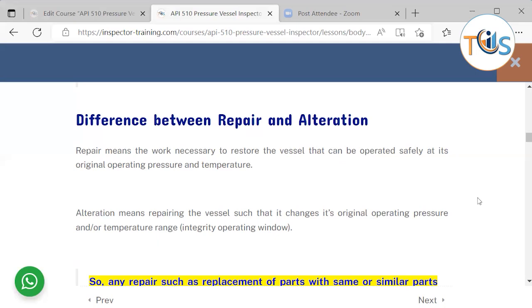Then you take some of the thickness reserved for the design pressure and bring down the working pressure, so that not as much thickness is needed as was originally intended. You use part of that thickness, which was reserved for design, for corrosion allowance, if you know the corrosion rate. So that's called derating.